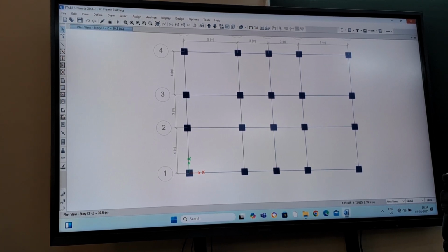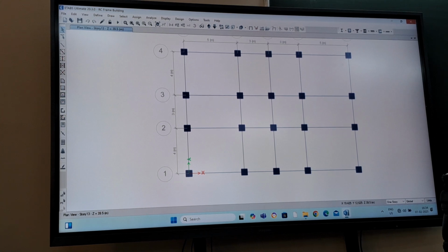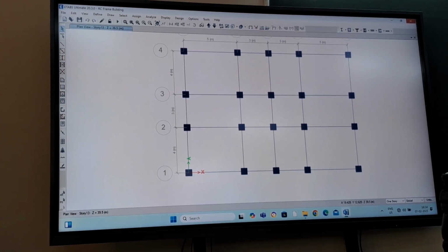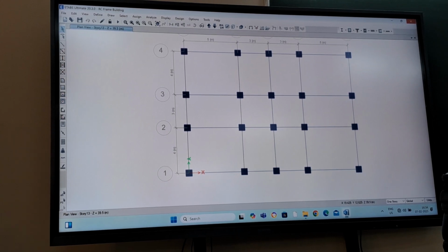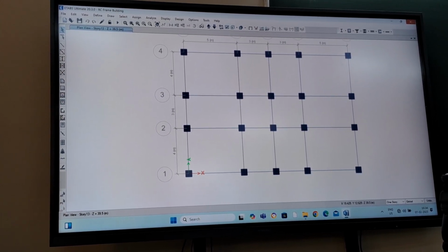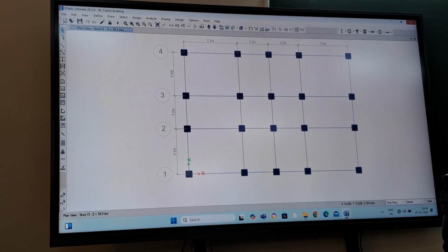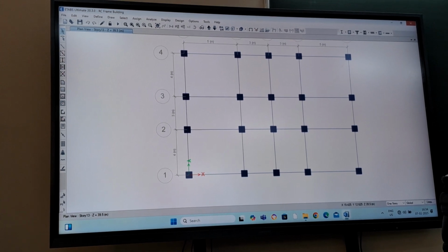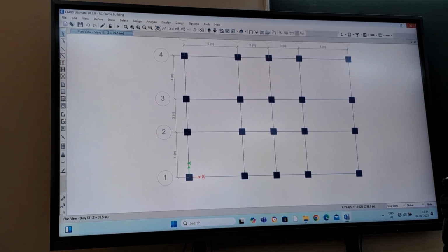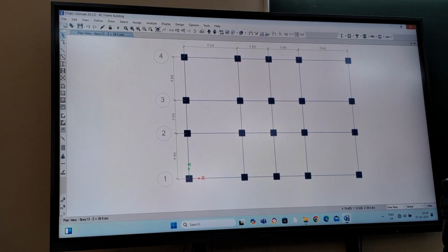Up to 50 mm, let's say, it is acceptable. Nothing will happen. In a normal situation also, when you are providing the splicing, what you do? You bend. One bar is coming like that, another bar is coming like that. Then you join and connect them together, right? There also you are providing this kind of bending. So if the requirement of bending is less, it will not affect the